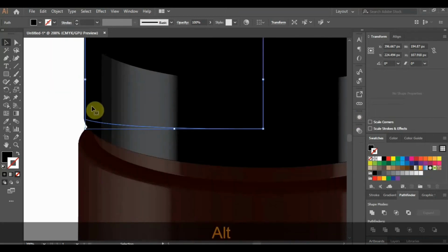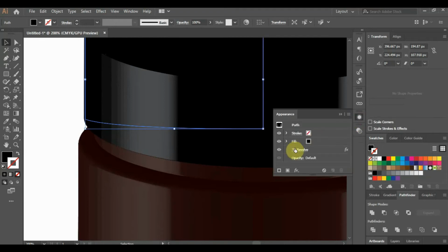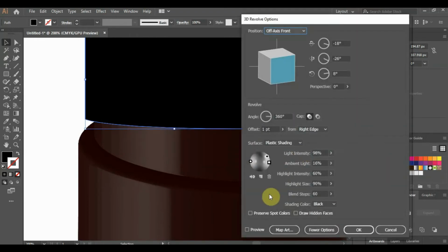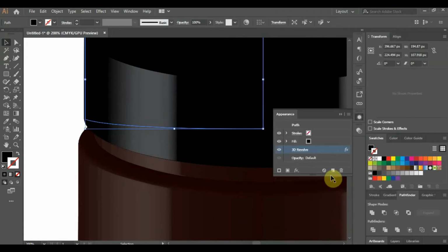See, now here you can see the glitches. There are some straight horizontal lines you can see. To rectify that, just increase the blend mode. The blend step should be increased. See, now it's almost gone. You can set it to around 200, 215, in between that.